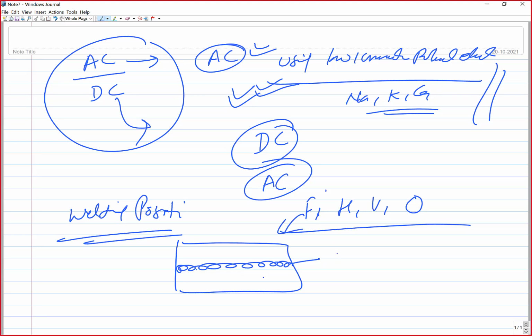In flat welding, there is no issue regarding the control of the molten metal, since you can easily place it wherever desired. So even if you generate high heat, it's fine, because the placement is easier.